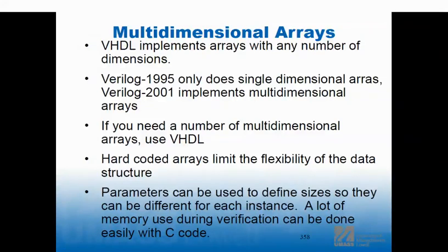But if you think of something like the scoreboard, you really need something like that, right? You need more than just the address and data on it. You need another dimension to search on, and it supports that. So you can't use it for the DUT. You can't use it for synthesizable, but in this world, fine. Behavioral code, multi-dimensional arrays work really well.